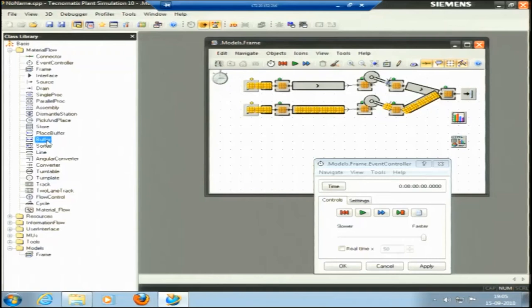The big buffer is placed between two plant components for certain purposes. It temporarily holds parts when the following components fail, when the successor is not able to receive the component. The second important function it does is it passes the part on when the preceding components stop working. The dimensions of a buffer with large enough capacity for covering all failures lead to complete decoupling of the plant and the other attributes as well.